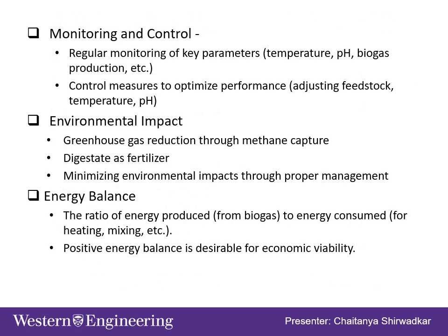The effective management of an anaerobic digester requires diligent monitoring and control. Regular checks on key parameters such as temperature, pH, and biogas production are essential for optimizing the process. By adjusting feedstock, temperature, and pH, operators can fine tune the system for maximum efficiency.